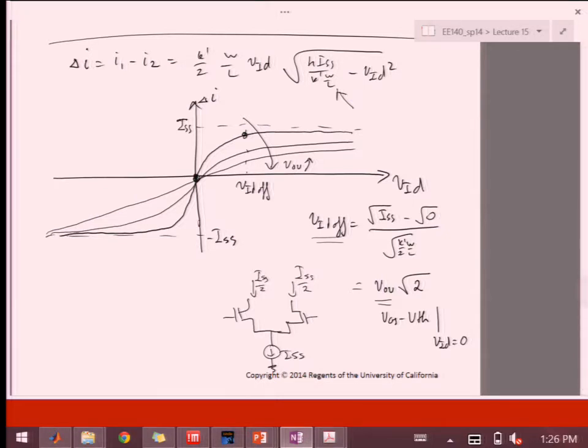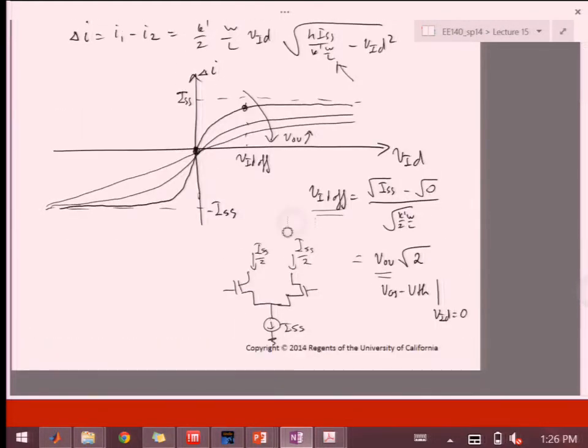And if that's the case, then I have essentially a similar behavior to that of a resistively degenerated bipolar transistor. Okay. So I have another knob with which I can sort of expand this range.